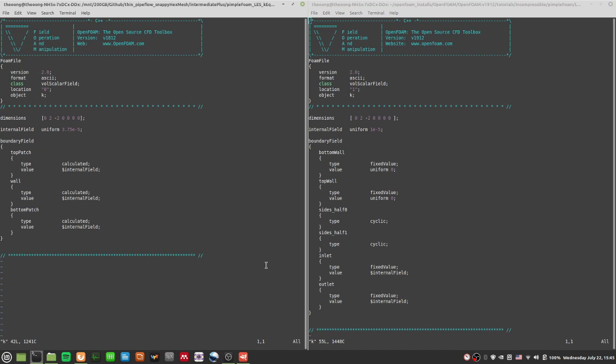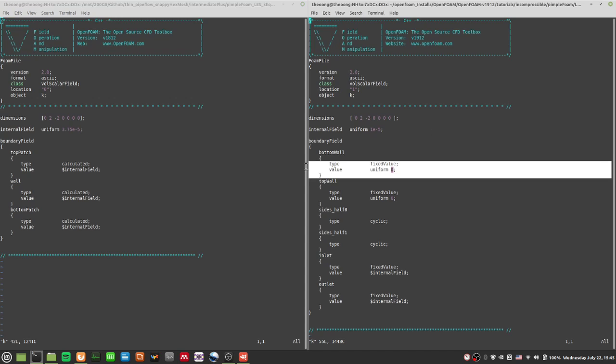Of course you have to calculate your own turbulent kinetic energy somehow, and the way to do it for LES is not the same way you'll do it for a Reynolds-averaged Navier-Stokes. Ideally you want to simulate 20% of the turbulence, so you want to put 20% of the turbulence in the turbulent viscosity kind of a manner.